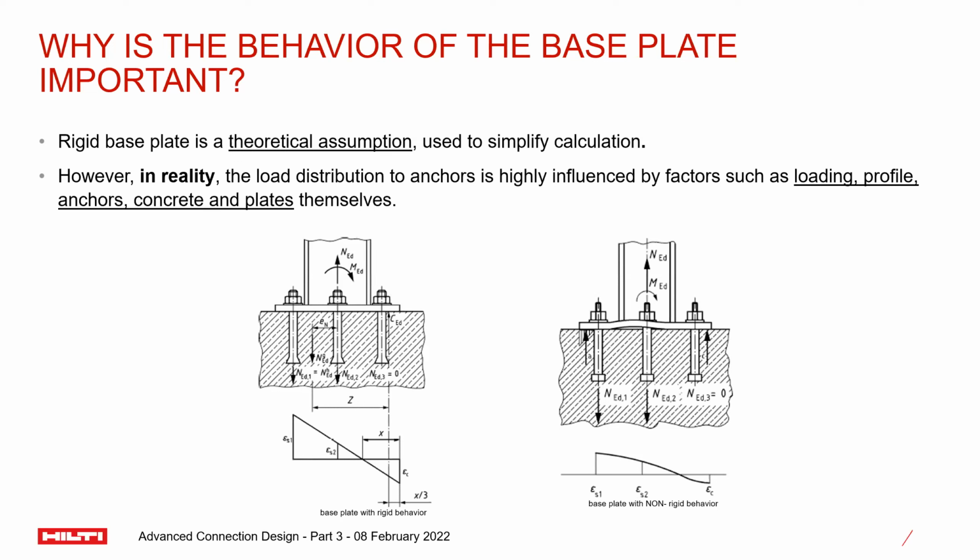Until now, whatever I said about the rigid assumption, we were always on the left-hand side world. And what happens in this world? Everything remains rigid, elastic, and linear, the three words you usually hear in every book when talking about base plates and strength compatibility. Base plates remain rigid, the behavior is linear, and it follows the linear elastic curve of your stress-strain graph. But is that realistic?